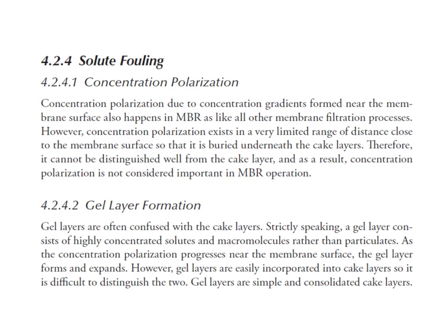And the main driving force for the gel layer formation is concentration polarization. However, gel layers are easily incorporated into cake layers, so again, it is not really possible to distinguish gel layer formation from cake layer formation. So we can just treat gel layer formation as a part of cake layer formation.